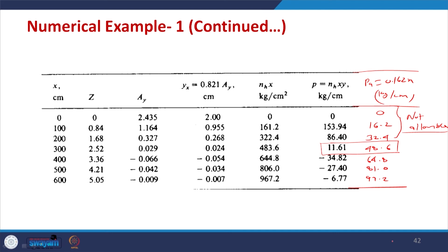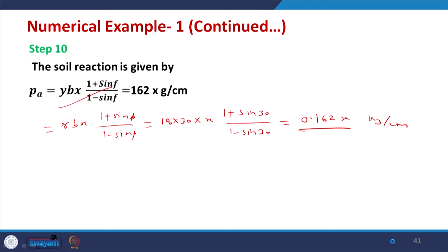So, this was the case when the pile top is free to rotate. In the second case, when the pile top is fixed against rotation, you need to change the value of Fn1. In this case, the factor FSL1 prime comes as 1 instead of 0.65. As a result, instead of 1.753, you get 1 divided by 0.65, into 1.753. So you will end up with 2.697.